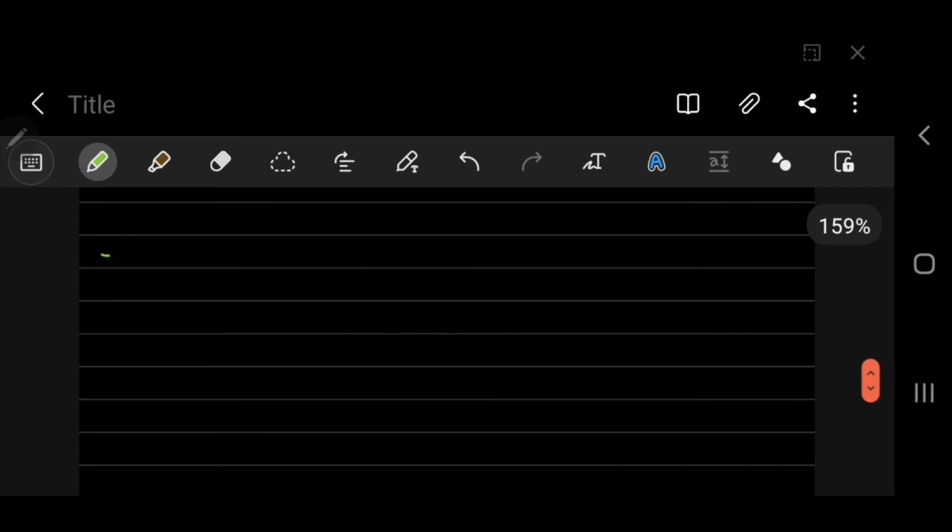Now there is one method which is mentioned in the book, that is the area for area method. I will tell it in a short manner. When we provide a space for an opening, like a nozzle or a manhole, at that time the material of the pressure vessel gets removed.